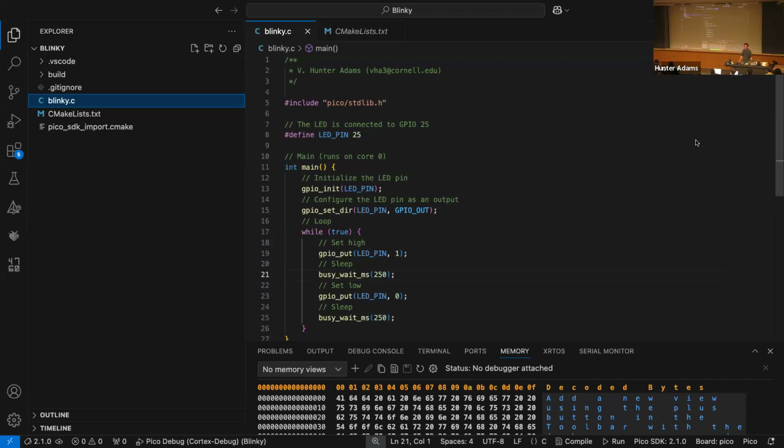And we demonstrated the mechanism by which, when you encounter a line of a program in this class that you are unfamiliar with or would like to learn more about, you learn more about what that program is doing. In particular, the first place that we went to learn about that particular C SDK function, gpio_put, was the hardware API guide, right? So we went and we Googled RP2040 hardware API.